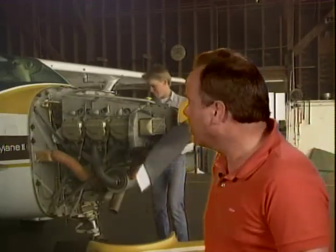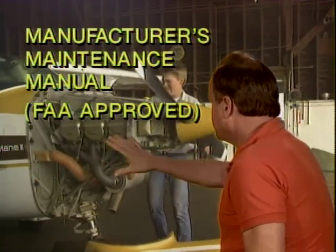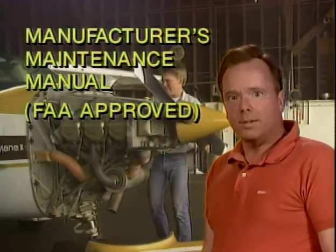Who determines these things? Well, the manufacturer's maintenance manual, when it's FAA approved, contains approved data for performing a major repair to an aircraft engine. So where do you look to find out what to do to repair an engine? The manufacturer's maintenance manual, because it'll be FAA approved, because otherwise you wouldn't be flying around in an airplane with it. So it's the manufacturer that determines a lot of these things.